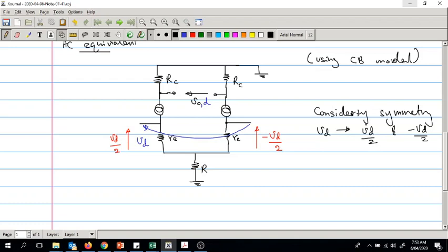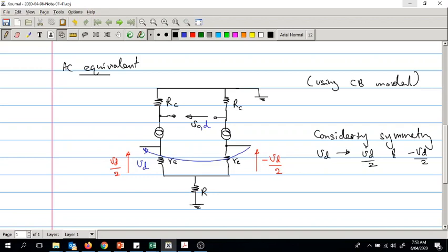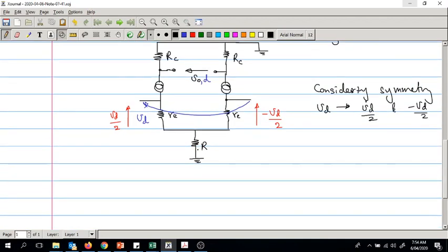two equivalent circuits, right? So in the case of equivalent circuits, we can take one side at a time. Now when it comes to the transistor, the differential input is given between these two, so therefore in the AC equivalent there won't be any current going in this resistor, so that resistor will also become not actually meaningful, right?